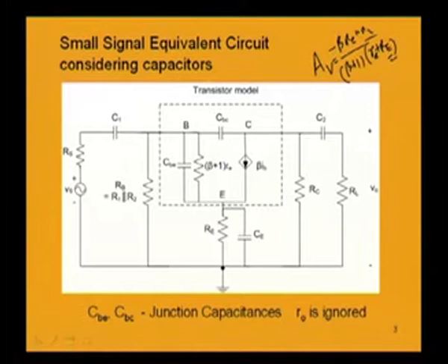So due to these two factors, there will be a voltage drop in these two capacitances. So your overall voltage gain, which is the ratio between output voltage and input voltage, or if we consider the overall voltage gain with respect to the signal AVS, it is V naught by Vs. Now this V naught without this capacitance will be higher than V naught with capacitance.